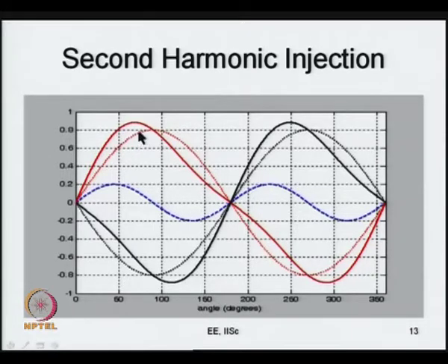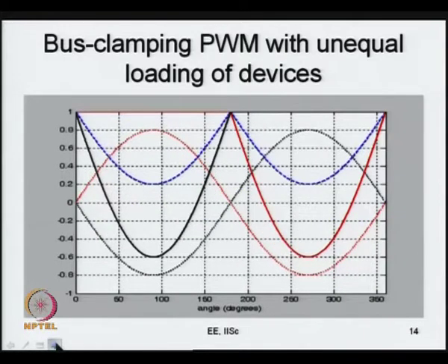So, there is no point essentially, you can, but nevertheless you can add a small value such that this peak value or this peak value do not go beyond plus Vp or minus Vp now. Okay. So, now it is possible to add fourth harmonic like this, sixth harmonic, eighth harmonic or anything, any even harmonic really like this now. You can add that in such a fashion that any signal which is at double the frequency.